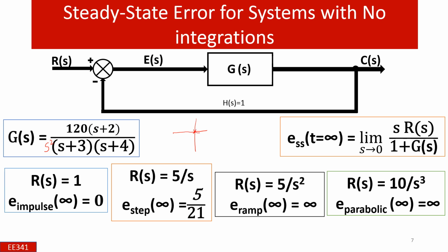And if we consider this concept in the time domain, there is some t raised to a power, with some coefficient here, and if we apply time approaching infinity, definitely its effect will be considerable, and it deviates from the results, and this makes the system unstable, and in this case the steady state error is infinite.